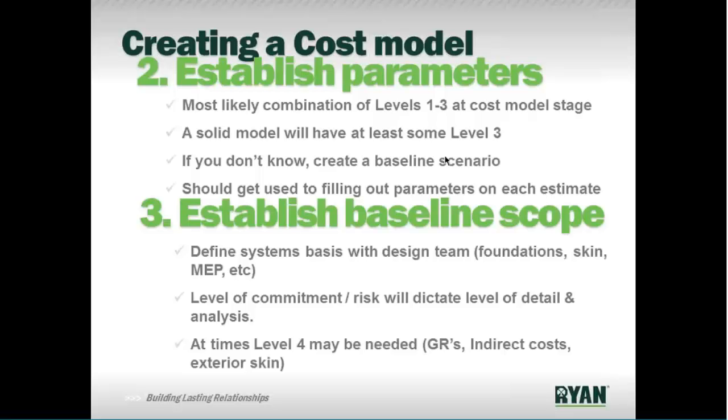And the last point there in terms of establishing the parameters is just a general comment that you should get used to filling out those parameters on each estimate, because regardless of which stage you're in, they're valuable for analyzing or just understanding things from a macro perspective. So from the first estimate to the last estimate, just get used to thinking in terms of ground floor area, elevated structure area, skin area, roof area, all those things that are listed on that parameters page.